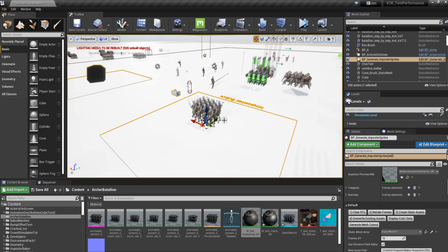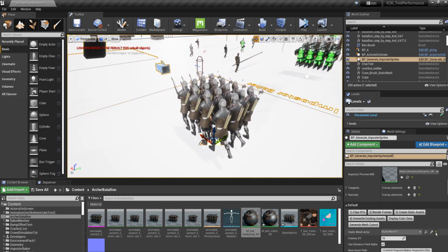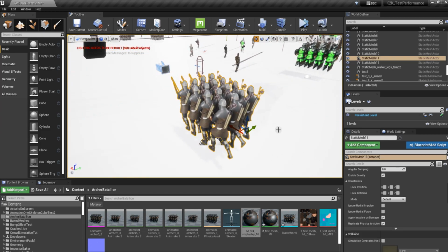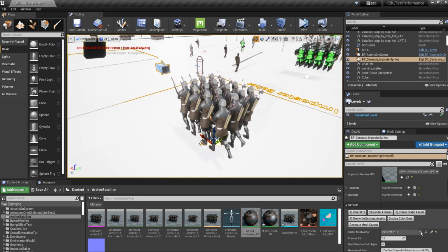Now we can finally bake it. Select the eyedrop icon to get the static mesh. You may check the cameras around, or withdraw debug spheres. Then press Clear RTs, then Render Frames, then Create Static Mesh.